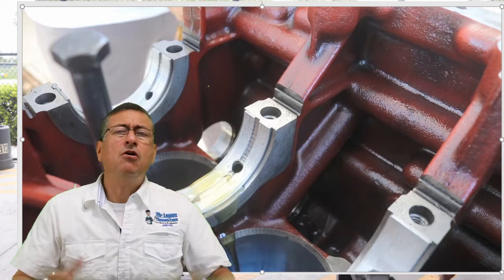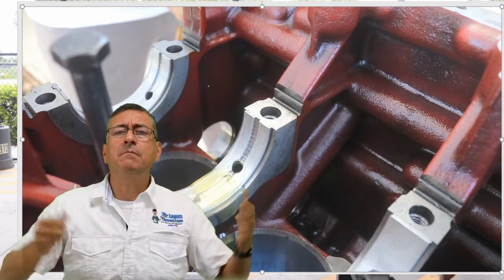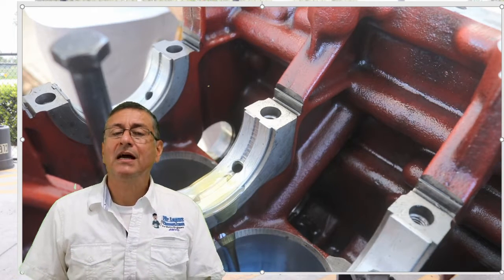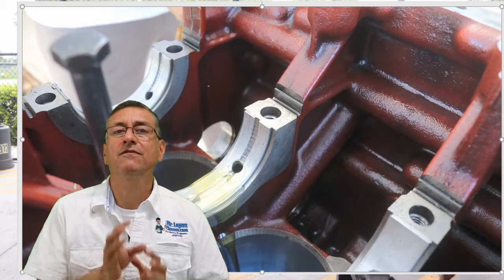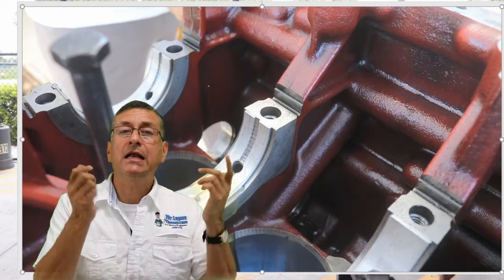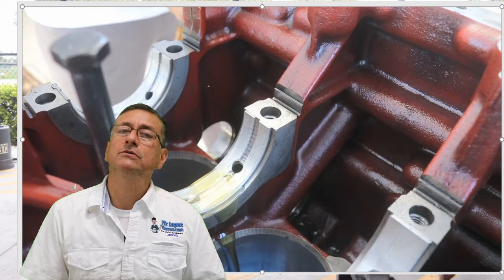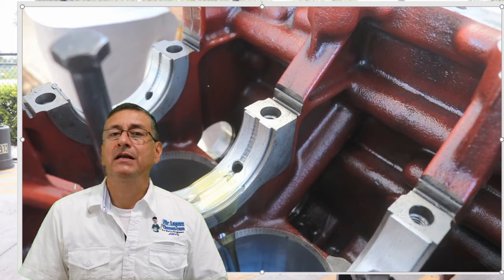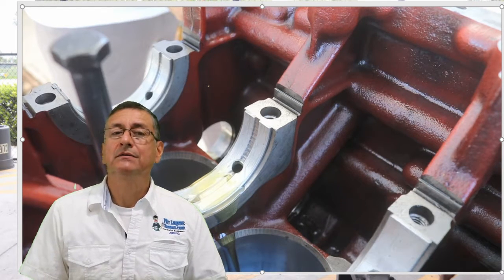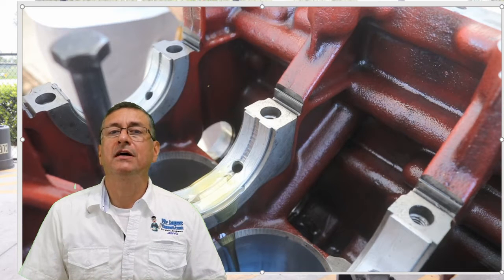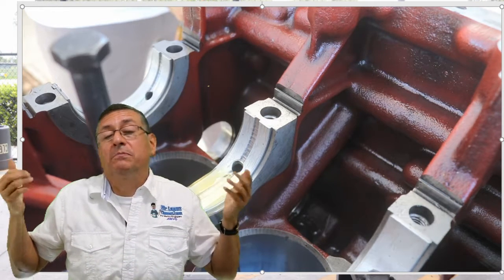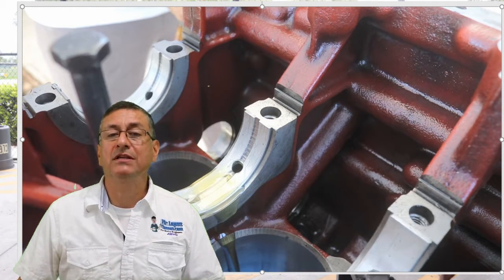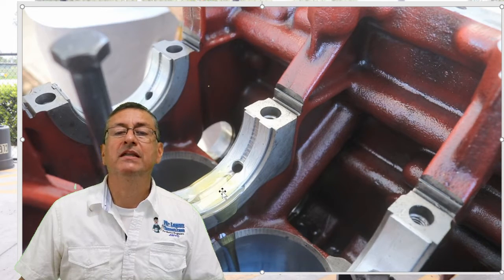For that reason, how can I verify the bearings? Do I need to disassemble the engine? No, not necessary. You can take an oil sample, and with the concentration of different metals in the oil sample, you can analyze the report and you can make a decision. Oh, I found too much lead, too much zinc. Oh, probably my bearings are worn. A little amount of copper. This is a perfect indicator that my bearings are worn, and I additionally have low oil pressure. This is an indicator that the babbitt in my bearings is worn. This is the babbitt, no? The soft metal, the white metal.